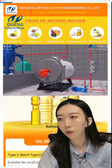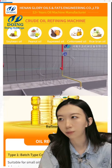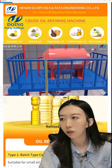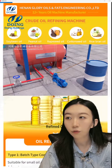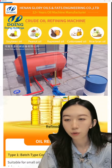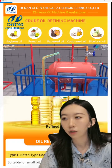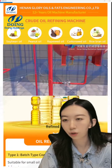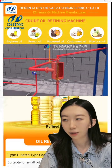And now this is the thermal oil circulating system. Before formal production, we should open the thermal oil recycling system. The conduction oil first enters the high level tank, and then naturally flows to the oil water splitter.